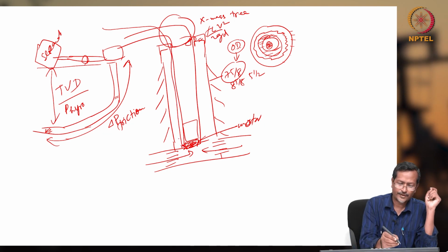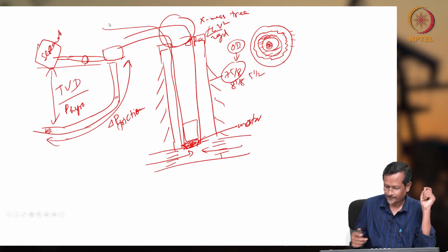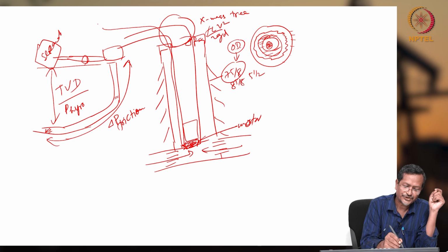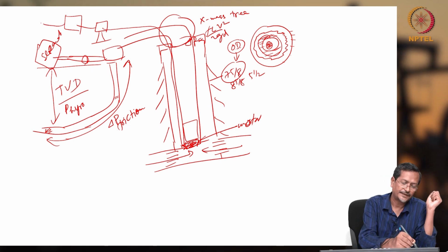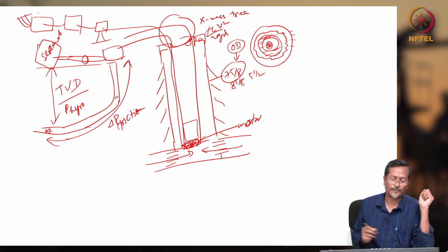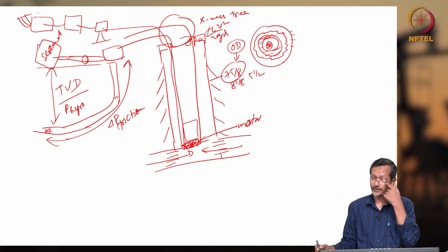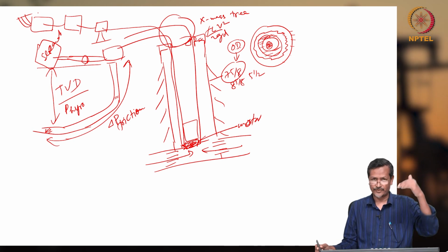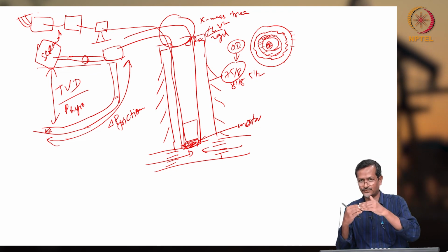So from the motor, first it will go to your junction box, right? Junction box to your switch box, VFD controller equipment will be there. Then there will be transformer to your high tension line. Okay, so let's say 11,000 volt you are giving, but you may not be requiring that much voltage. So you have to reduce, a step down transformer will be there. So it will be reducing volt from 11,000 to maybe 440 or 4,000 volt.